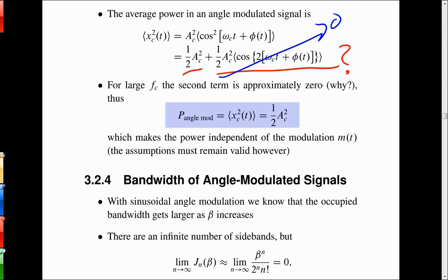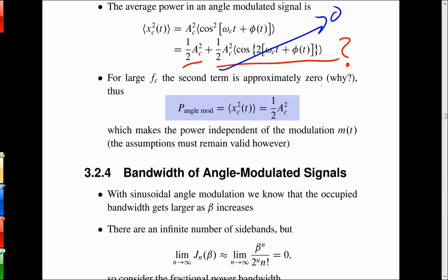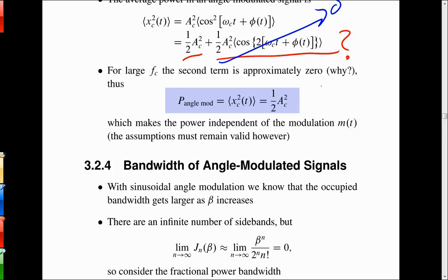So if you clip off these fluctuations and make them a constant, you don't really destroy the information. And that way you can get away with very efficient amplifiers, especially on a spacecraft which is running off of a solar and battery supply, but yet has to produce enough power to relay information back to ground. So they prefer to have amplifiers that can be very efficient, running close to saturation to make the conversion of DC power to RF power as efficient as possible.